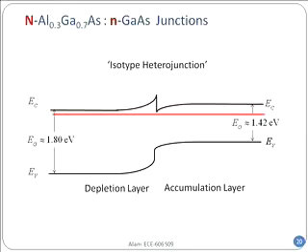And therefore, you cannot use the depletion approximation we used to calculate xn and xp. Remember, those are supposed to be purely space charge, where the mobile charges have been pushed away, and only the donors have been exposed and the acceptors have been exposed. And in that case, we could calculate those charges.